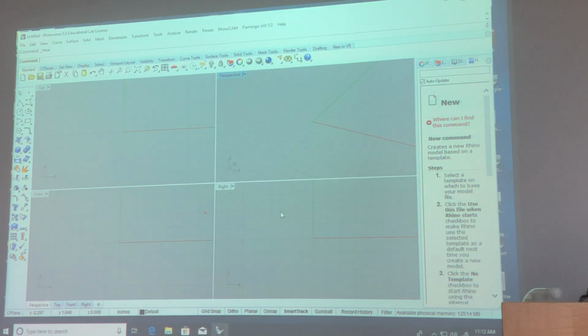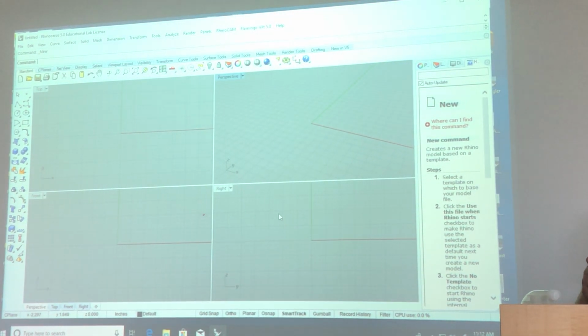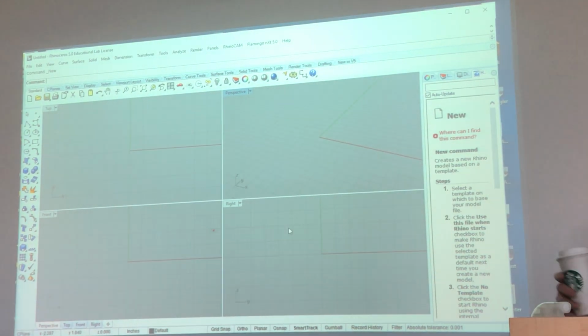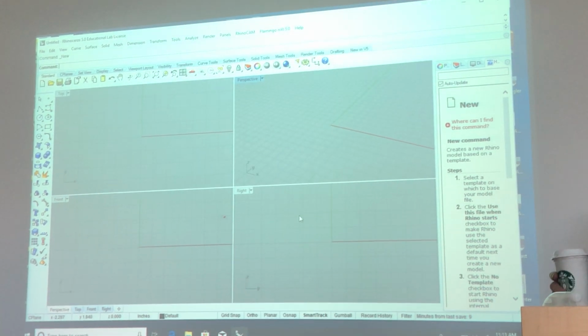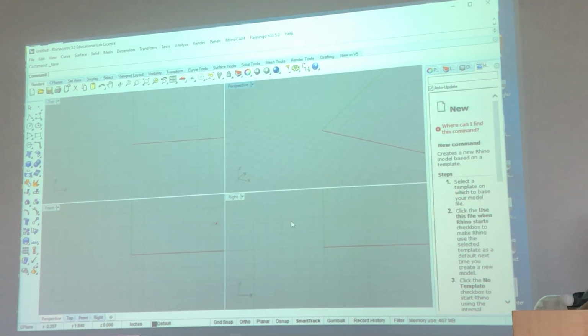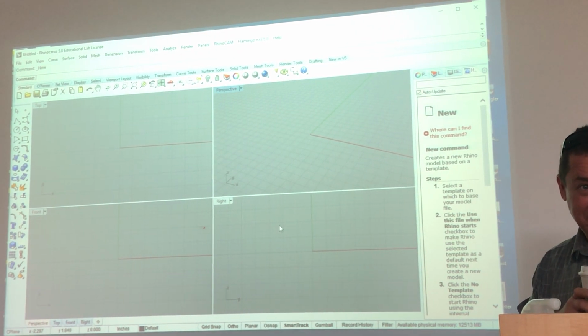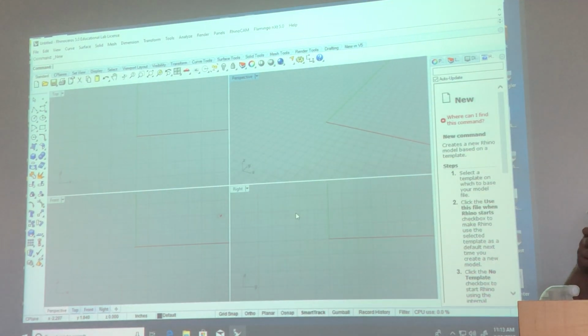1 divided by 32? 0.032. 0.03125. That is less than 0.05, and you will not be able to print a 6-inch wall at 1/16 of an inch equals 1 foot. How wide is your interior wall?